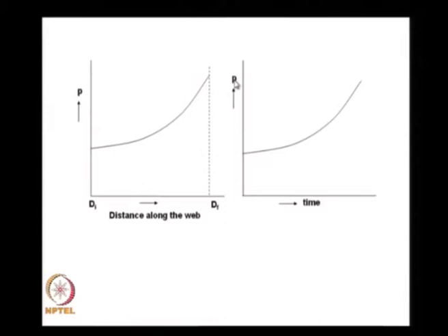Therefore, I was able to plot pressure as a function of time, and we find that the thrust of this grain, thrust going as C_f times P times A_t, keeps increasing with time as shown here. Therefore, this is a progressive burning grain. This is what we did in the last class.